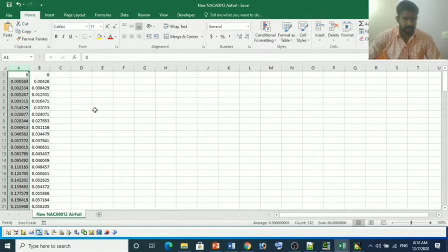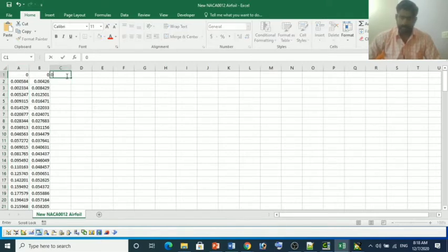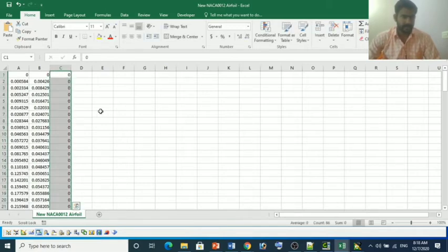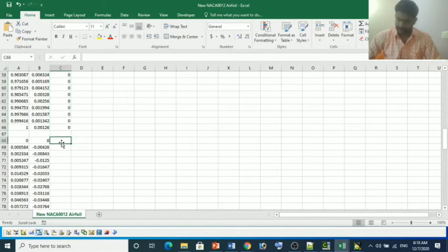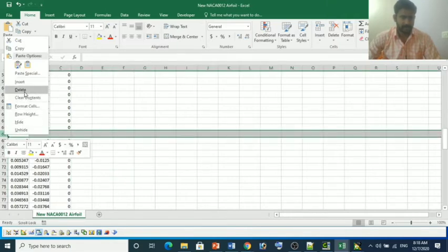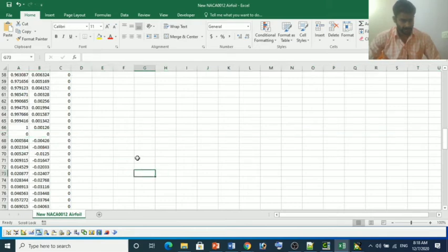Delete this one. In Gambit it will take every point in three-dimensional format. Here they mentioned only the x coordinate and y coordinate, so we need to add the z coordinate over here. We will consider two-dimensional, so in the z direction this will be 0 for all the cases. Again here also the 0. Anyway, we will delete this point, no need.